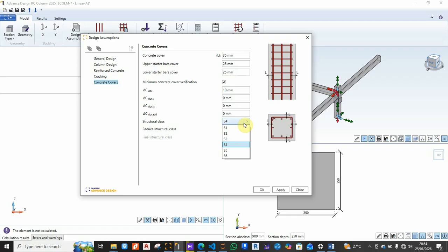So we cannot use a common cement. That's the first thing. And the type of cement influences the structural class. Secondly, something like a building has a 50-year lifespan design. Now, how about a bridge? You can't design a bridge with a lifespan of 50 years. No. So the type of element, its lifespan, influences what? The structural class.